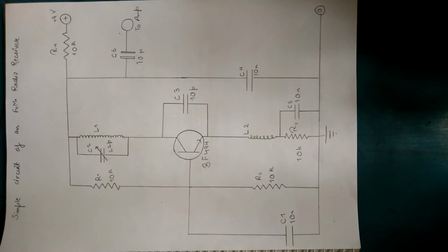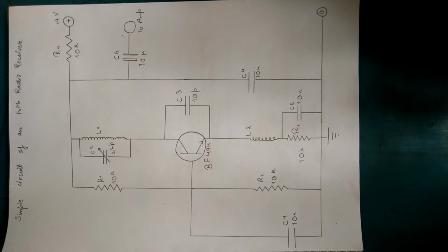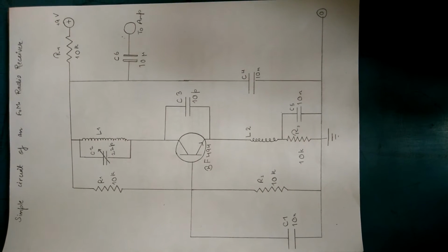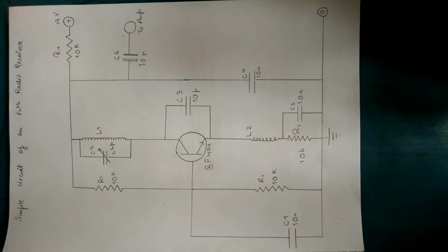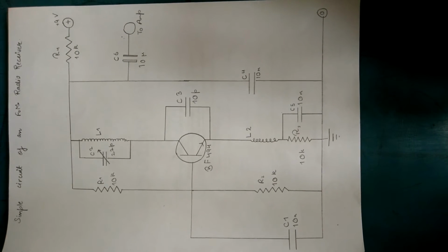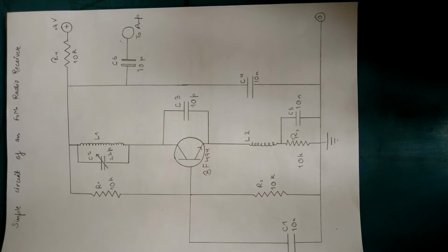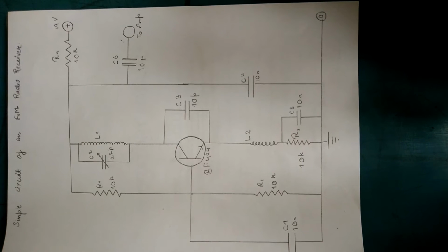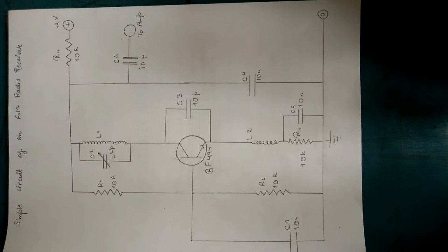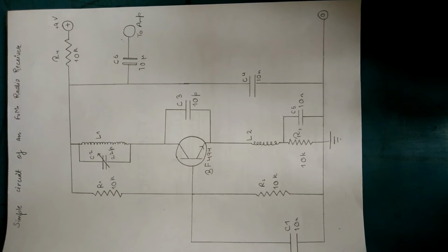It's basically based on a super regenerative audio receiver circuit, where the use of minimal components becomes the main feature of the unit. However, fewer components also means a few compromises are involved. Here the receiver requires a large metal base for grounding the unwanted signals and for keeping the noise factor to the lowest. Also, this system would work only in places where the reception is rather strong and thus may not be suitable in areas where the signal strength is thinner.